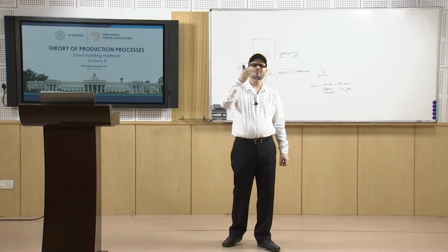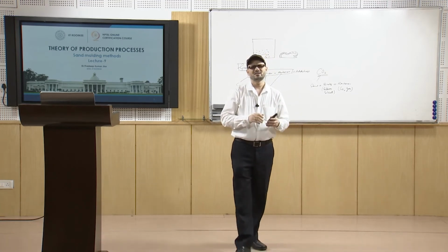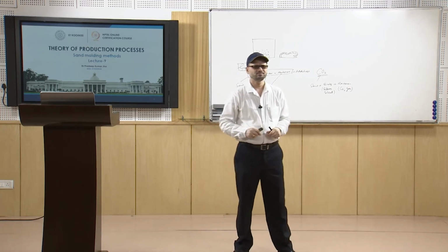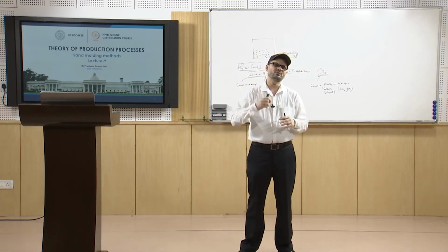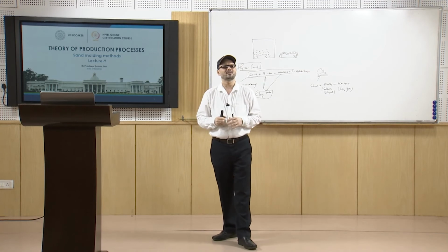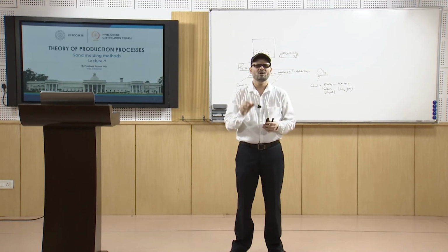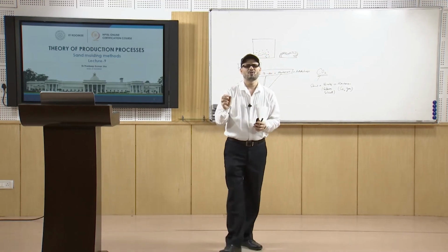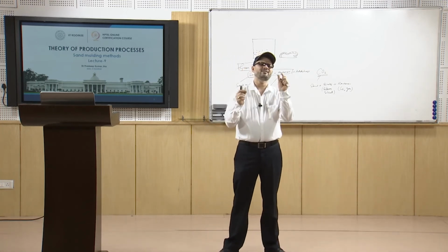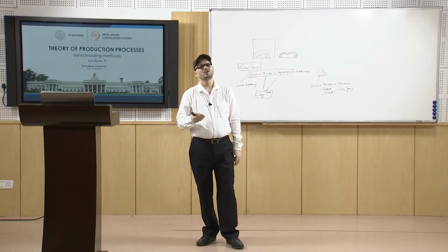Similarly, in green sand molding, after the molten metal is poured, the moisture will be driven off and slowly the metal will solidify and then you can take it out. In dry sand molding, we dry the mold, and one way is to skin dry the mold. In skin dried molds, the drying is done only up to a certain depth from the inside, maybe 3 to 4 mm or 5 mm, depending upon the conditions. You dry the skin and then you pour the molten metal inside. That is known as skin dried molds.